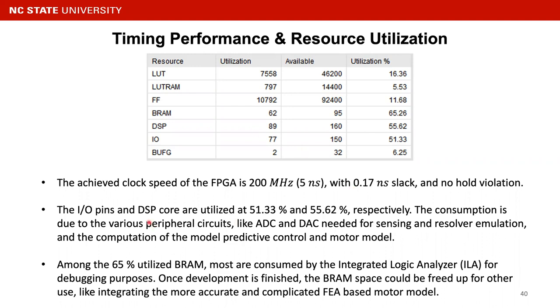The high utilization of the DSP core is mainly due to the intensive computation of the model predictive control and the motor model. And among the 65% utilized BRAM resource, that's the block memory, most is consumed by the integrated logic analyzer for debugging purposes. Once the development is finished, the BRAM space will be freed up for other uses, like integrating a more accurate and complicated FEA-based motor model.